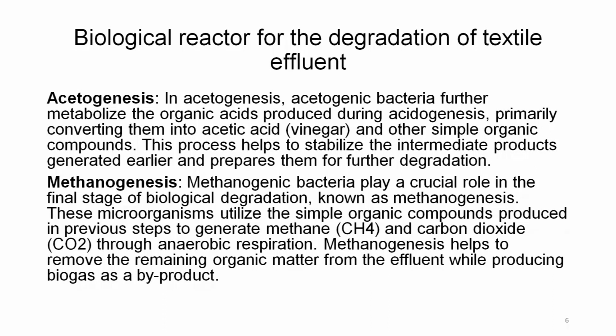Methanogenesis. Methanogenic bacteria play a crucial role in the final stage of biological degradation known as methanogenesis. These microorganisms utilize the simple organic compounds produced in previous steps to generate methane and carbon dioxide through anaerobic respiration. Methanogenesis helps to remove the remaining organic matter from the effluent while producing biogas as a byproduct. So, it is also an advantageous byproduct that is formed during methanogenesis.